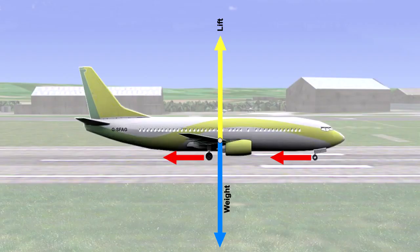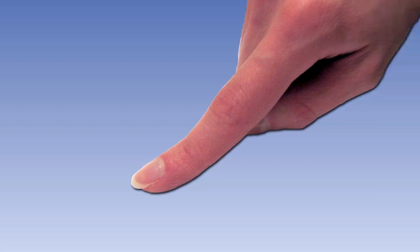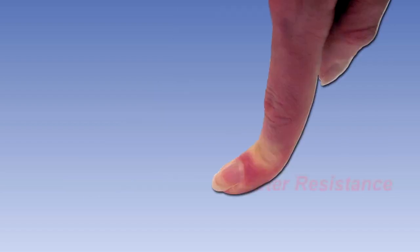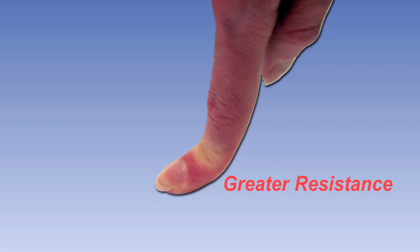Having discussed aerodynamic drag, let's now consider wheel drag. Wheel drag is basically the friction between the wheel and the runway, and is a function of their friction coefficient and the load placed on the wheel. As an example of this, press your finger lightly on the desk and push your finger forwards. You will notice a resistance to the motion of your finger. Repeat this scenario, but now press down harder. You will notice much greater resistance to the motion of your finger. This example aptly demonstrates that the greater the load placed on the wheels, the greater the wheel drag.